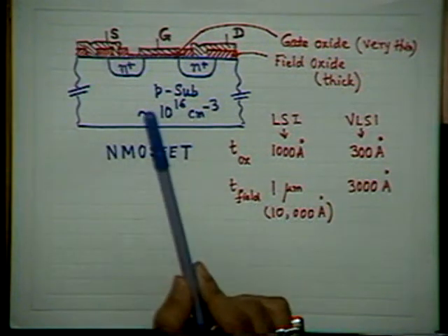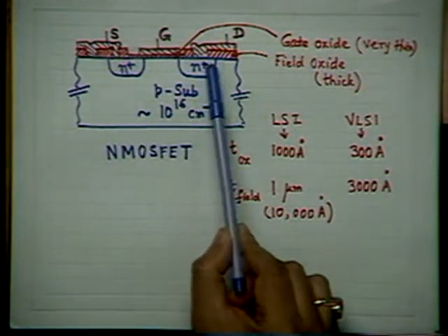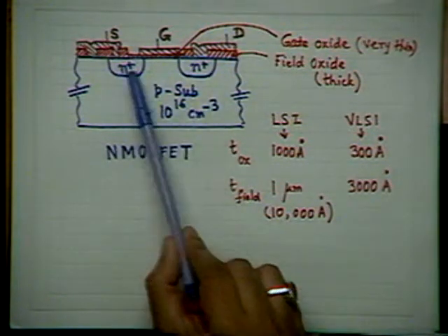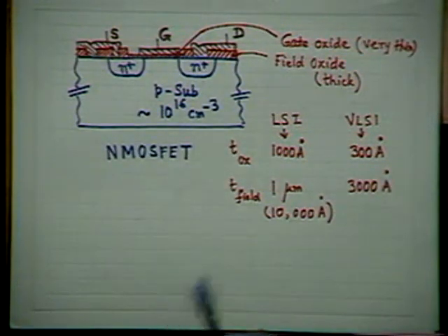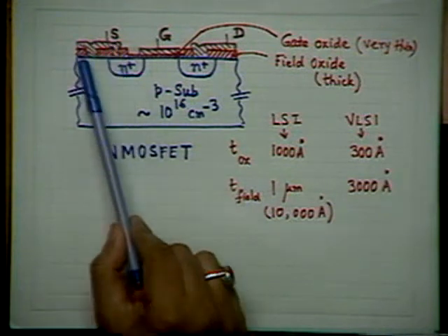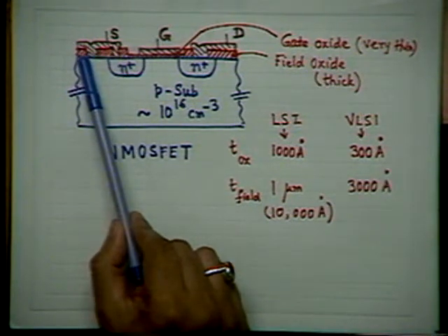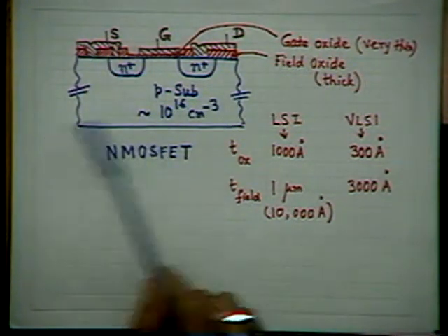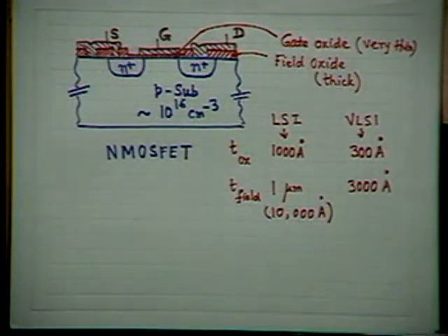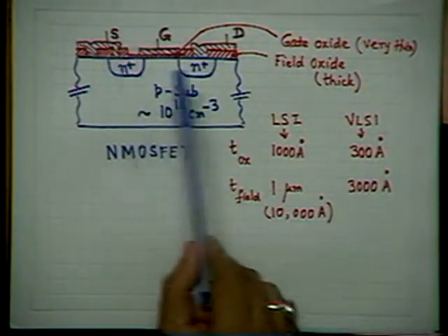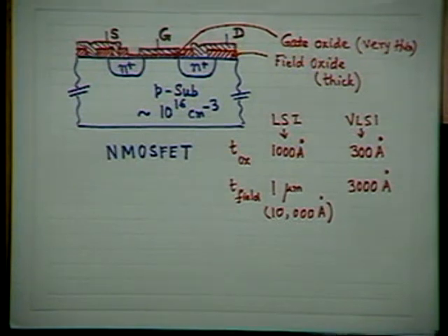Otherwise, this MOSFET is a bilaterally symmetric device. If I short-circuit the source to the substrate, it becomes asymmetric after fabrication. But otherwise, you see that you can interchange source and drain, which you cannot in a BJT. In a BJT, you cannot interchange emitter and collector.